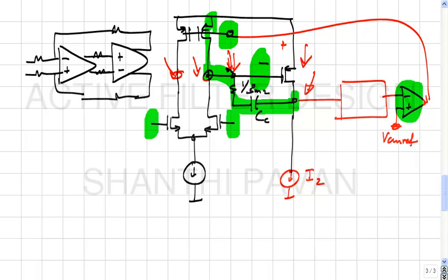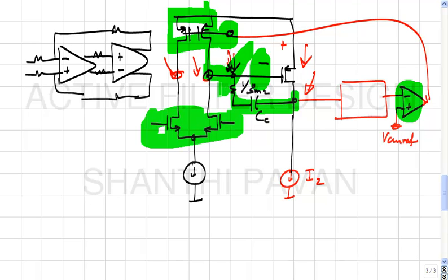And unbelievably, there is a fix around this. The problem, as you can see, is that when this guy is cut off, there is no communication, but one part of the loop is like physically cutting the loop, right. So it doesn't really matter if the common mode feedback error amplifier is going crazy, right. There's no loop to go and fix, correct. So you can think of some circuits which will go and kick this node even when the input